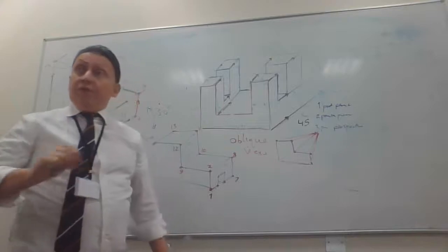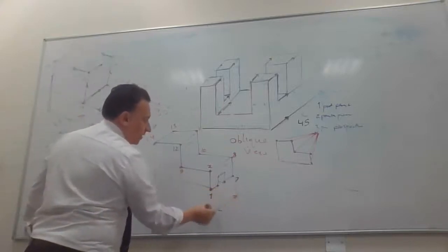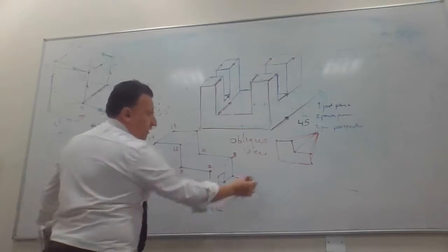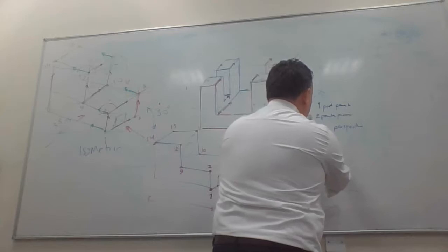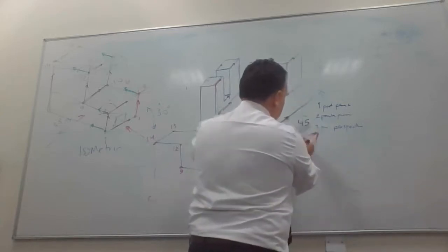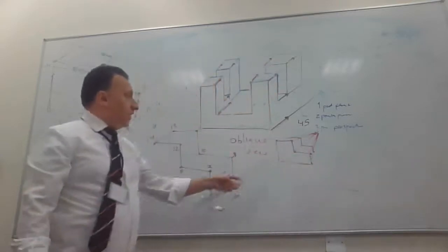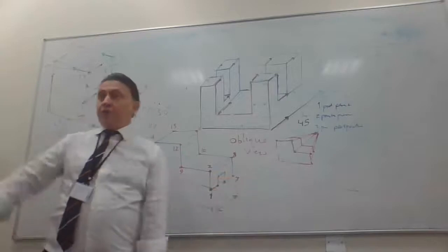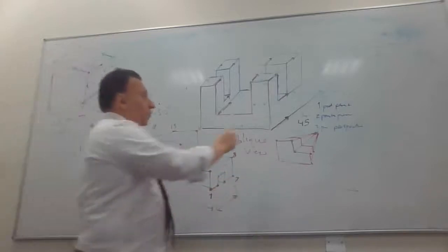After you match, you have to decide the thickness from here to here. What's the thickness? In this case, I will assume it to be here. Now you have to draw vertical lines and horizontal and vertical and horizontal. So I draw this one based on perspective view. This is called 1 point perspective. See?